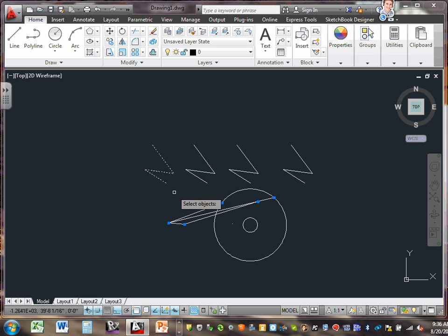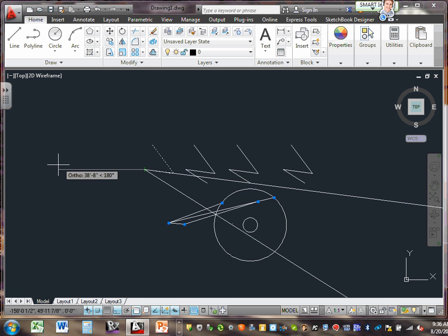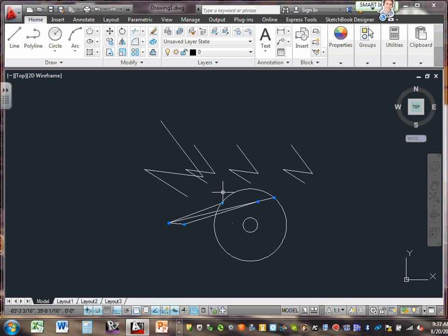So pick it up, right click, put the point you want to scale it from. Pick any point. I'm going to scale it from this point. Can you guys see that? Can you see now it's going bigger? How much do you want to scale it? If you type 2, that will double, basically scale it twice. It becomes twice as big. And hit enter. Now I have scaled the object twice as big as it is.